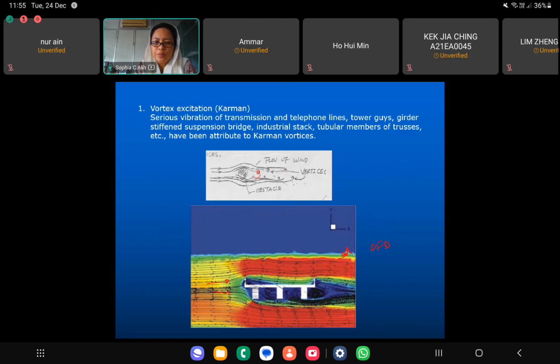And this is the wind blowing over this side, and it is a little bit dark, but actually you can see the vortex excitation over here on the side. So when you have vortex excitation that you can see from the CFD, you can check how much is the pressure caused by the vortex itself, right? So this is the velocity of the wind, and if your structure is sensitive to vortex, again you have to check on this pressure on the other parts of your structure.